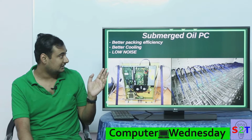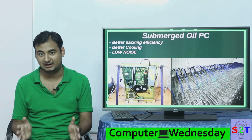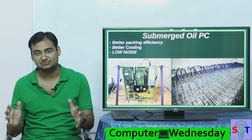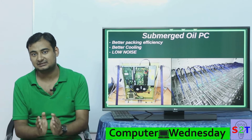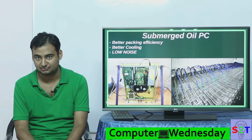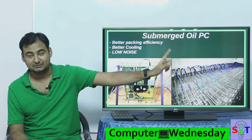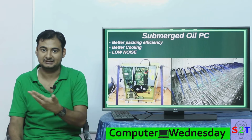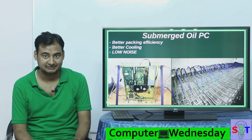Second, you have to understand packing efficiency is very crucial. The land area that you have to buy for your server is very crucial. You want to take as much money out of it as quickly as possible. For that reason, you want to put as many servers as you can in the square hectare that you bought. So for that reason, the packing efficiency of this is also higher. Not because you can't pack air cooling as close to each other as this. It's simply that an air cooler will get roasted by itself. The air does not conduct heat away quickly enough.